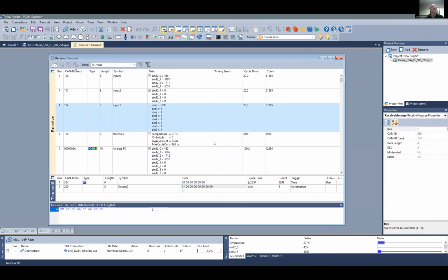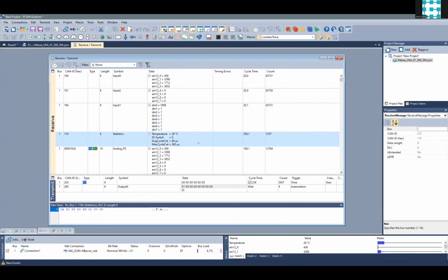What you can do inside the script, you can get the information of every CAN connection. If the bus is healthy, you can see the error frames and the error counter. We can have different limits of errors which are allowed, and the CAN still will work. Normally it is moving up and down. You can read this and you can act and reset the CAN channel, for example. That's possible. In the scripting, you can do nearly everything. But then I need exactly what the customer needs, and they can contact us on the support, and we have samples, and we can send the samples to them.